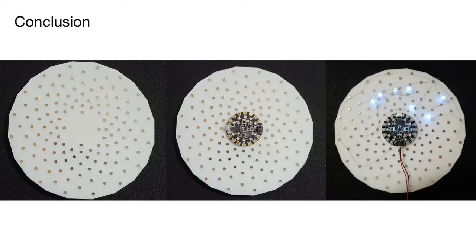In conclusion, the ThreadBoard is a rapid prototyping platform for E-textiles that utilizes a system of magnets. Incorporating magnets provides a prototyping platform that is more appropriate for E-textiles than the solderless breadboard. Makers no longer need to work with single-use snap connections or maneuver alligator clips onto small pins. Rather, they can now lay circuit traces with conductive thread.